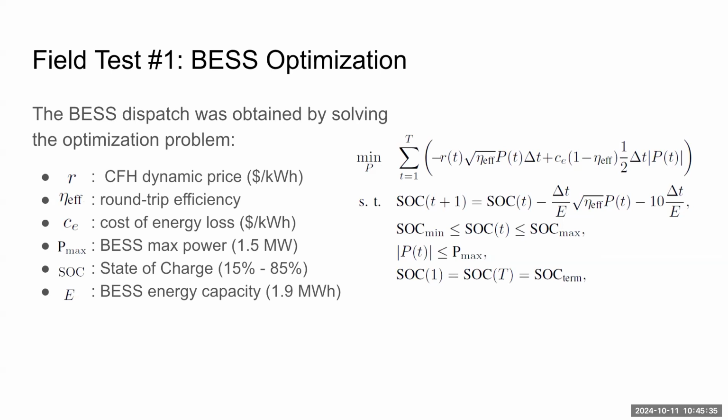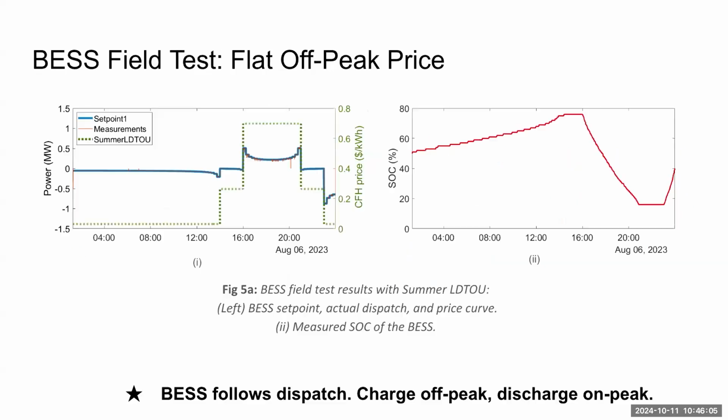We also have to think about losses. So there's some terms here that tell us, well, if we use the battery more often, then actually we have more losses. So we actually have to use more energy. So we also have to account for that. But this first term, R times P, that's really the key ingredient here. And then in optimization, you have constraints, which means you have to restrict what the options are that you can explore. So for batteries, you usually have a maximum and minimum charge state, so it cannot go more than full and less than empty. And same for electric cars. So these are the constraints. And then you can now calculate what's the best way to run my battery.